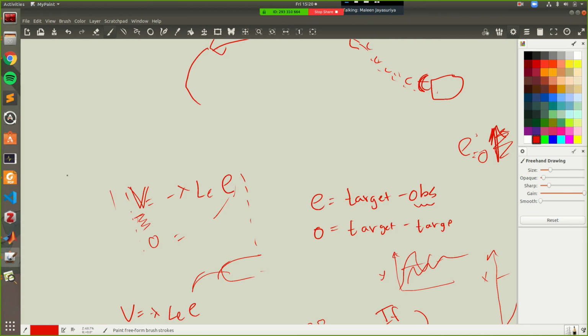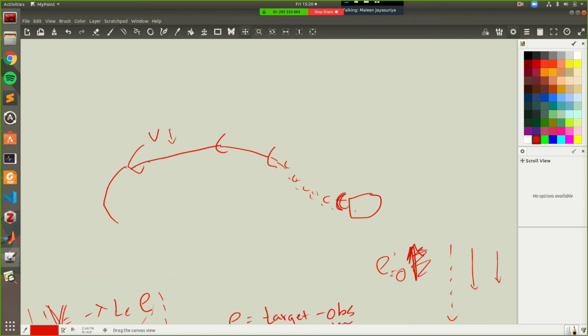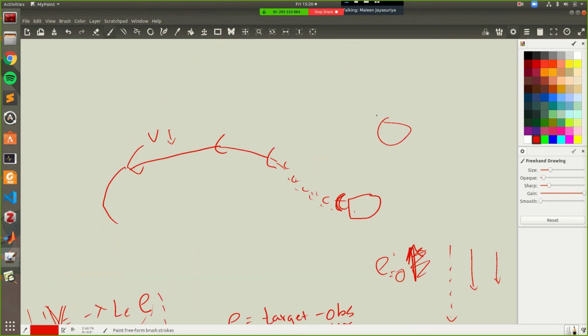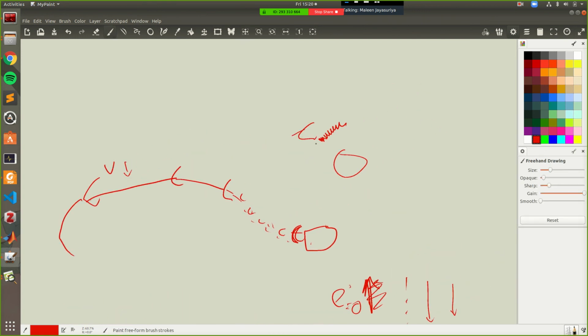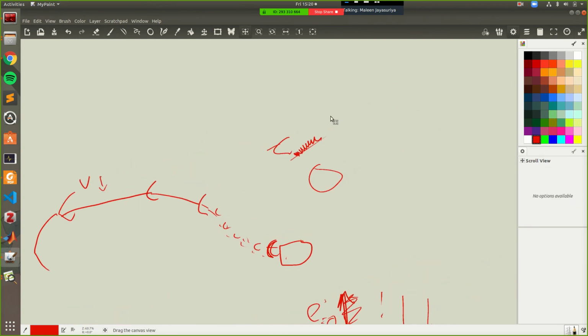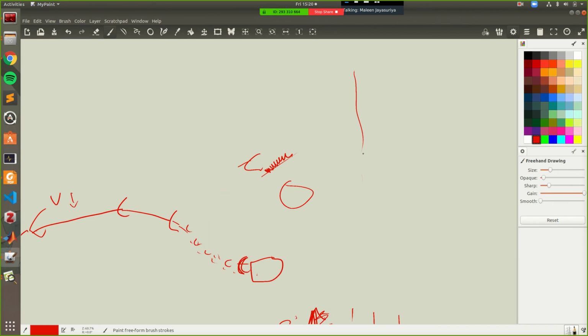Those things are called heuristics. You can decide certain conditions for when you want it to stop. If you implement this and realize that the system can never reach 0, and it comes close to the object and just starts moving a little and oscillating like that, then obviously you can set some sort of condition to stop that from happening. Which is why understanding how the output behaves is important.